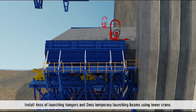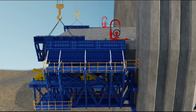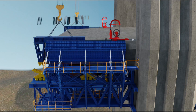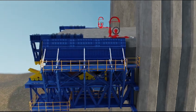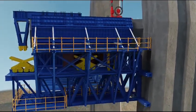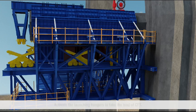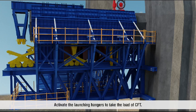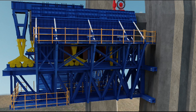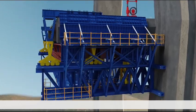Install 4 numbers of launching hangers and 2 numbers temporary launching beams using tower crane. Activate the launching hangers to take the load of CFT. Release and lower the temporary casting hanger inside the main frame and park it for the next segment casting.